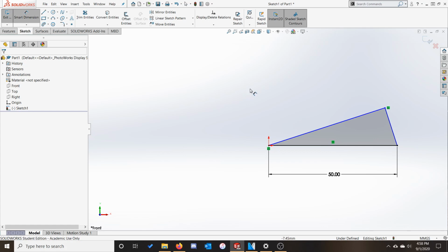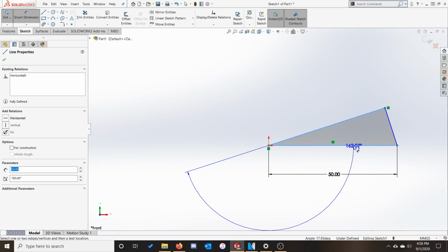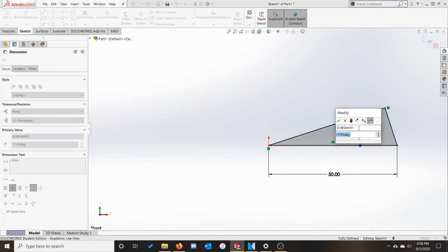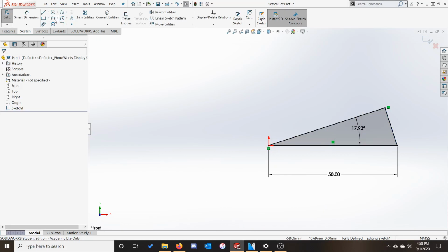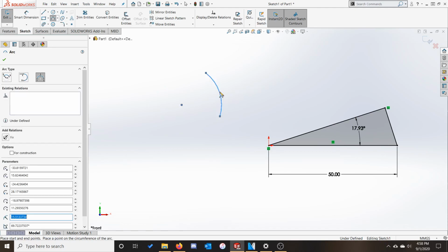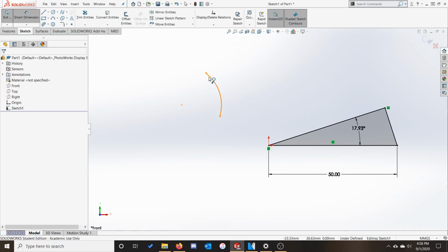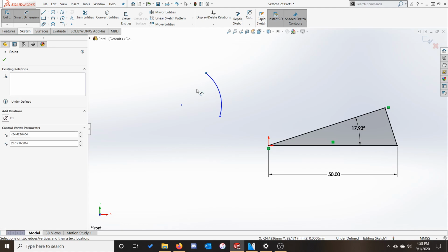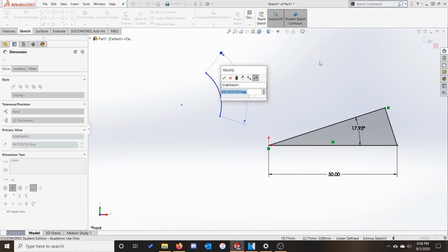We can also define angles using the Smart Dimension tool. When you have two non-parallel lines, you can select them both via left-clicking, and then select one more time to place the dimension. Another option, particularly powerful with arcs, is that we can use three points to define our angles. With the tool active, we can trace out an imaginary triangle by going from extent to center point to extent, and then left-click once more to place our dimension.